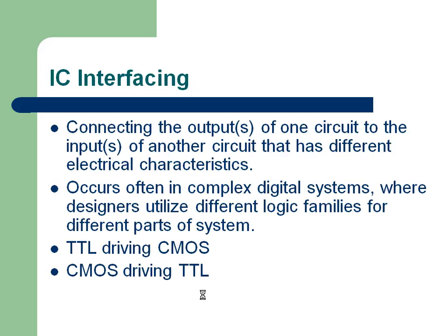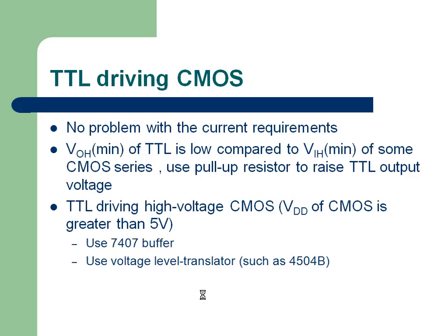But usually when it is an off-chip digital connection, it is quite likely that it is a mixed logic family. Driving could be TTL, driven logic could be CMOS, or it could be other. In that case, what are the issues? If TTL is driving CMOS, most of the time there is no problem with current requirements. Right? CMOS does not take currents. In case of CMOS, it does not have an absolute current threshold that I need this much minimum current to switch. You give some current, and based upon that current, only the input capacitance charging time will differ. That's the reason there is no problem with current requirements.